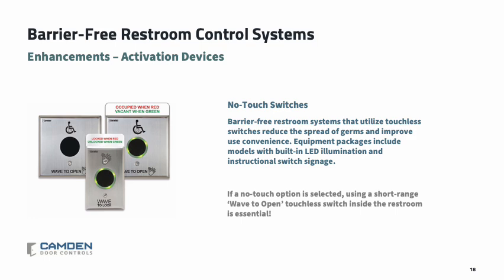If a no-touch option is selected, using a short-range wave-to-open touchless switch inside the restroom is essential to prevent false activations. False activation would result in a door opening before a restroom occupant is ready. Short-range models are designed to be immune to reflective surfaces and to be used in confined spaces that are typically found in restroom applications.